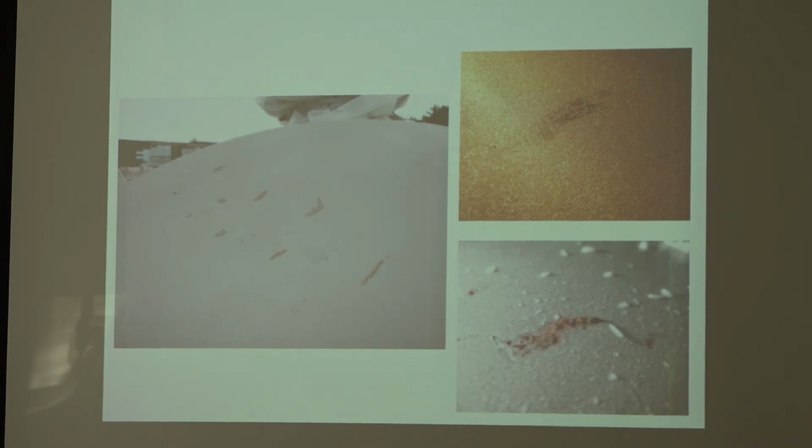And there's a little test. You see it becomes pink. You clean it off first, you put a little solution, and you look to see if there is any native iron that is not combined with the chrome or the nickel. So you're able to quickly identify that it's not a pitting problem.